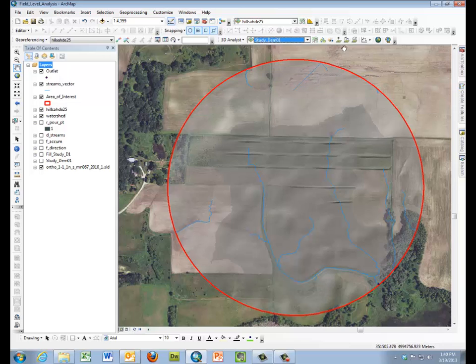Now we're going to be using the Interpolate Line, which is this tool, and we're going to be drawing diagonals or perpendiculars across our stream to see some stream cross sections. I use the tool to draw a stream cross section perpendicular at this point. And perhaps I'm going to draw one perpendicular at this point.